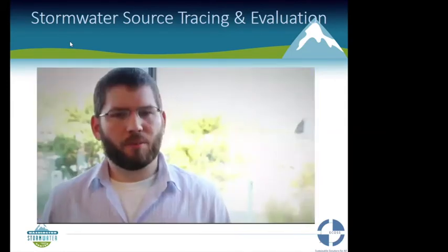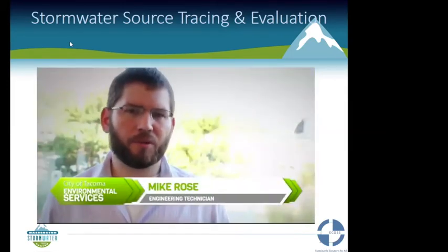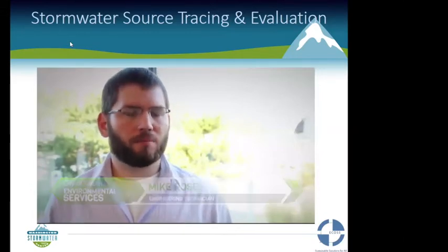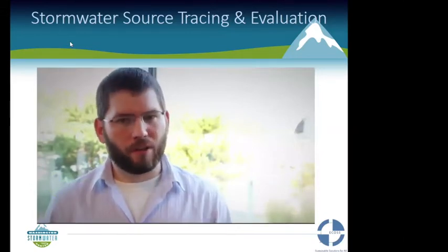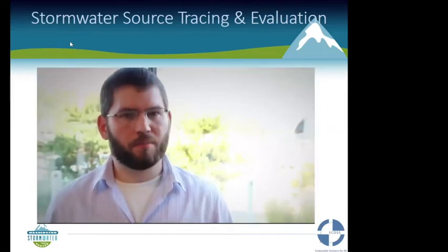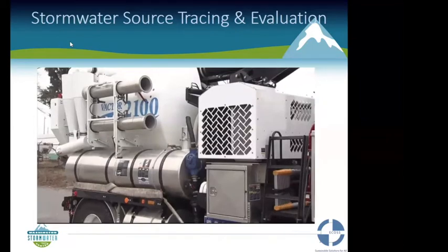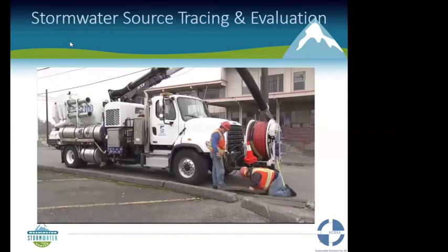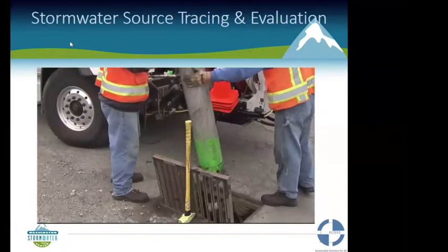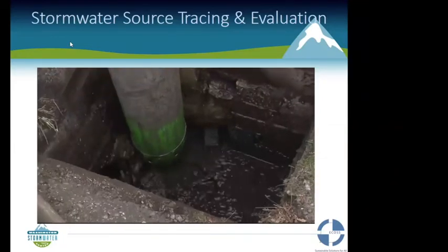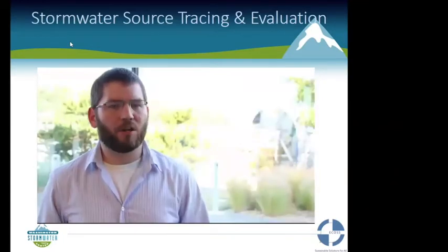So during the cleaning operation, the first thing we do is we want to block the line. So we have an inflatable balloon type structure that actually inflates inside the pipe and prevents any material or water moving down the line. The next step is we set up one of our Vector trucks, which is just like an oversized shop vac, essentially, if you're trying to visualize what it actually is. Once we have the line corked off, we set our Vector truck on that location.